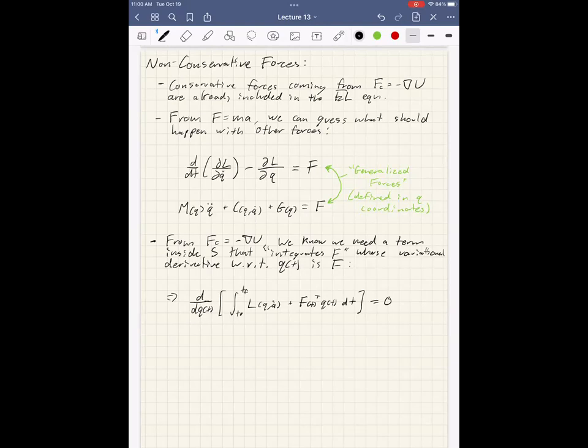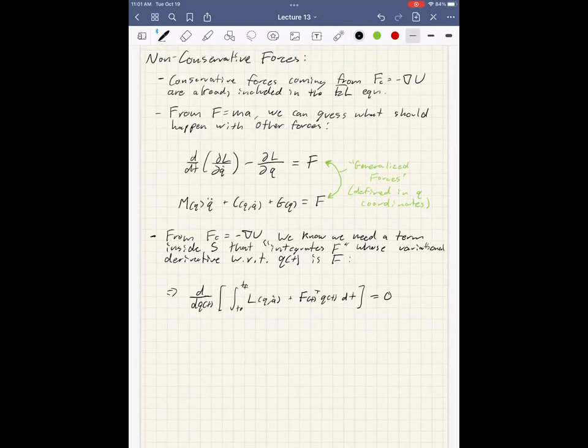But later, if I have a feedback controller that is a function of the state or whatever, and I plug that in, we can do that. It just so happens for the purposes of this derivation, you have to treat this thing as an exogenous force that's not a function of the state for this to work. So that's a quirk.